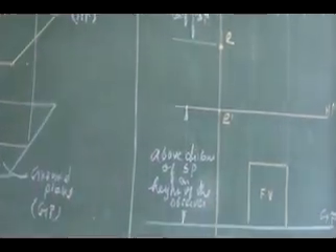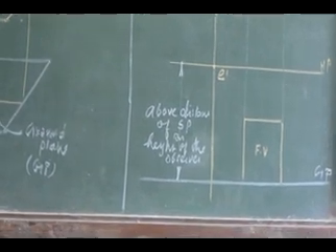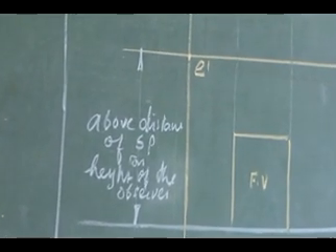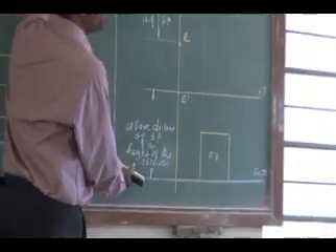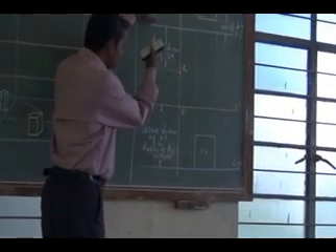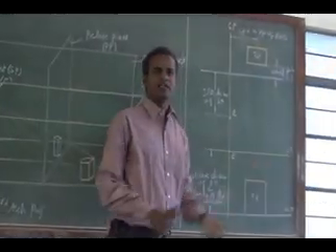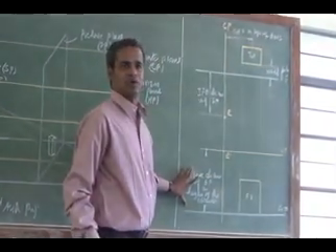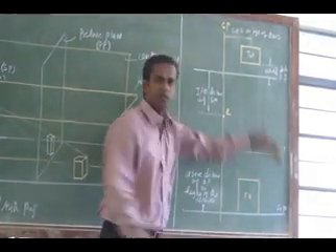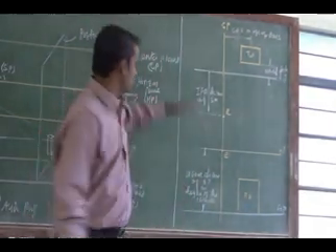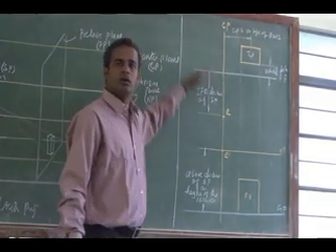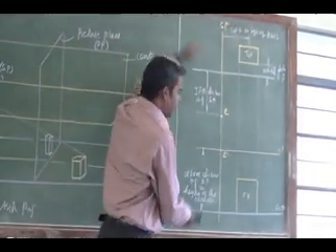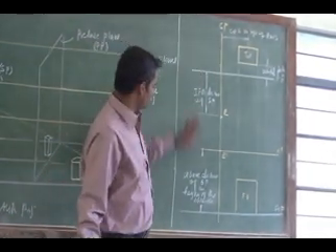So this layout is known as the third angle projection. The top view you have to draw on the top, and the front view you have to draw below. This gap between the GP and PP, the picture plane gap, you have to give sufficiently. What is the maximum gap I should have, including this and this? Approximately you give 150 mm. Try to draw the ground plane at the bottom of your drawing sheet and the picture plane on the top. You maintain the gap in between, which is the summation of these two.